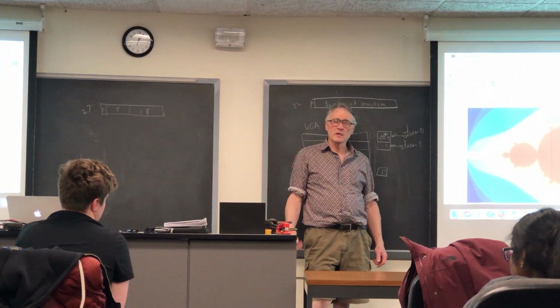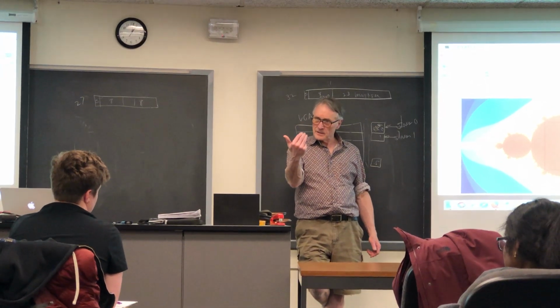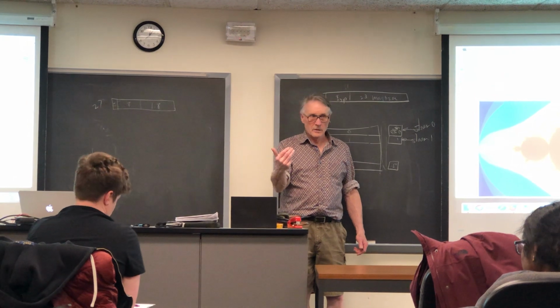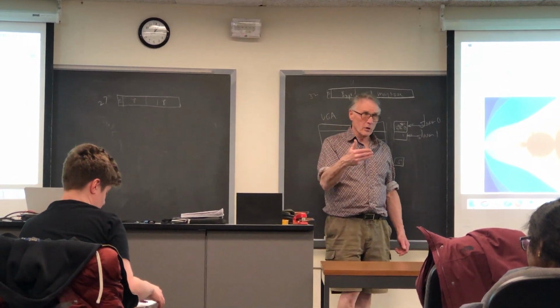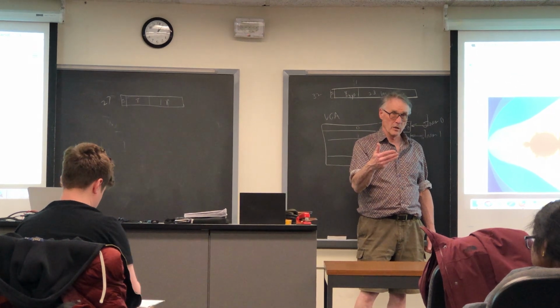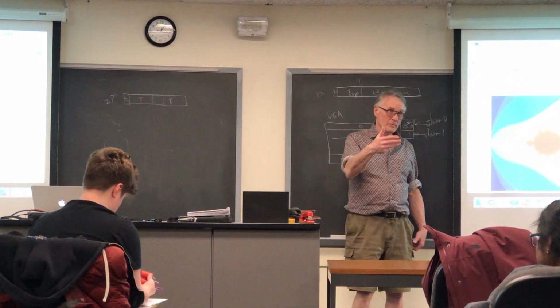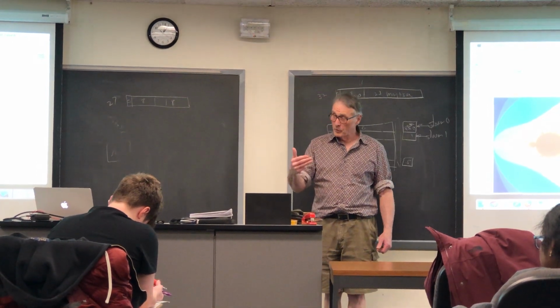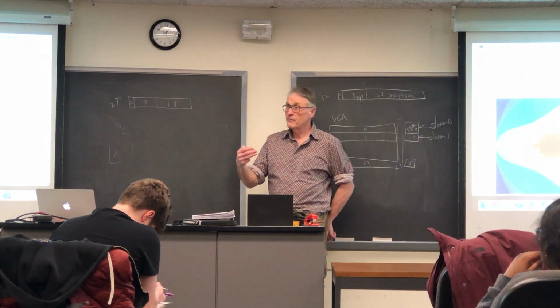So what that says is, you'll read back a color index from memory, which will be either an 8-bit or a 4-bit index. Then you'll have a lookup table, which will convert each index to a different color. Then that lookup table output will go to the I-red, I-green, and I-blue inputs of the VGA controller.